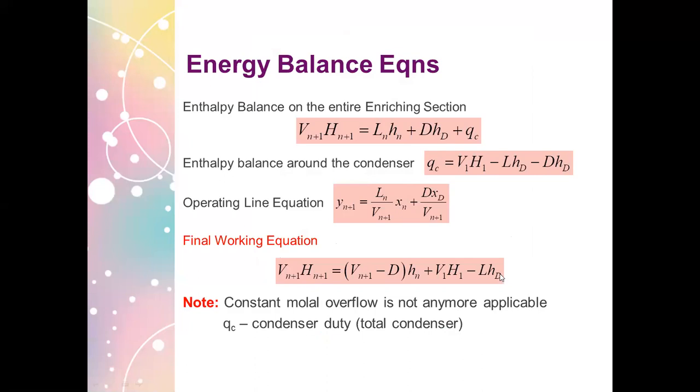However, if you would just be asked by the problem, what is the condenser duty? If all of these are readily available, anyway, the enthalpy of the distillate is based on the mole fraction of the component in the distillate. I'll be showing you the enthalpy diagram next meeting if we don't have enough time now. So this would be your condenser duty, an equation that will solve for the condenser duty. The energy balance for the enriching section would be this one, taking into account already the condenser duty.